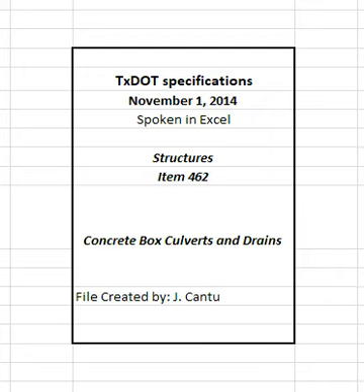Excavate, shape, bed, and backfill in accordance with Item 400, Excavation and Backfill for Structures, except where jacking, boring, or tunneling methods are shown on the plans or permitted. Jack, bore, or tunnel in accordance with Item 476, Jacking, Boring, or Tunneling Pipe or Box. Immediate backfilling is permitted for all box structures where joints consist of materials other than mortar. Take precautions in placing and compacting the backfill to avoid any movement of the boxes or damage to the joints. Remove and replace boxes damaged by the contractor at no expense to the department.